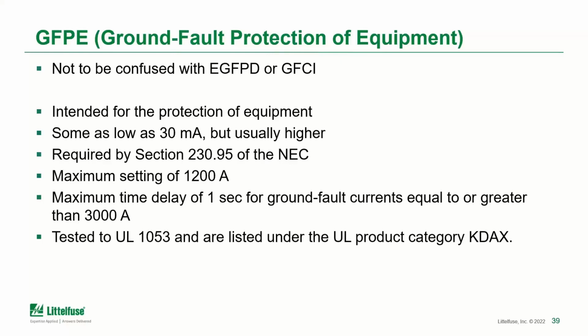So on a system, NEC section 230.95 is where it talks about this. And really it's often set in terms of amps or tens of amps or hundreds of amps. And the product category here is under UL 1053. So these are paired with circuit breakers.